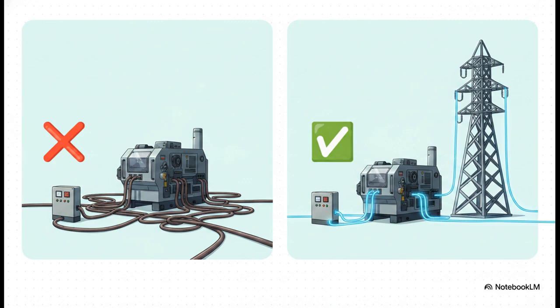In an unoptimized layout, your MCC might sit way far away from your heavy machinery. That means you need massive, incredibly expensive, thick electrical cables running everywhere, kind of like a giant, messy bowl of copper spaghetti. But in an optimized layout, you strategically place that motor control center near both the power grid and your major high-power users. This keeps those power lines remarkably short. Thick copper wire eats up capital incredibly fast, so keeping those runs as tight as possible, that's just brilliant economics.